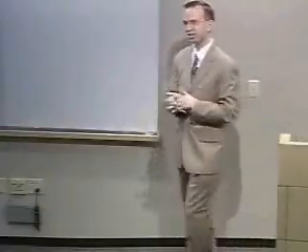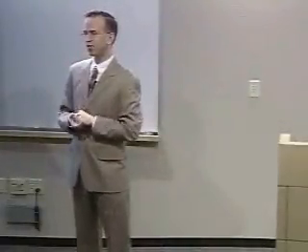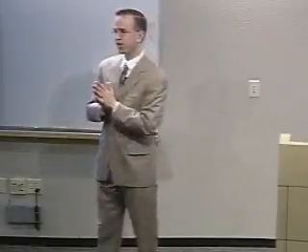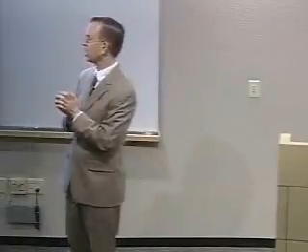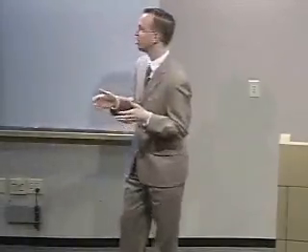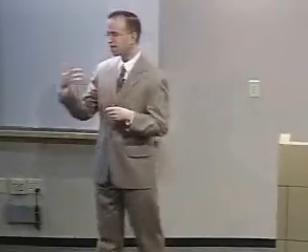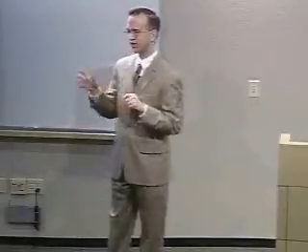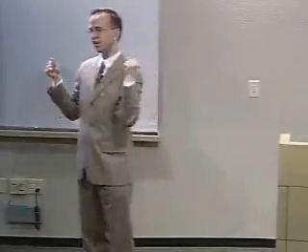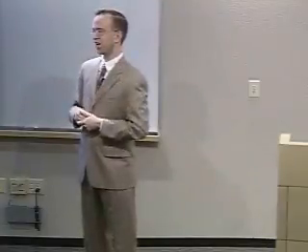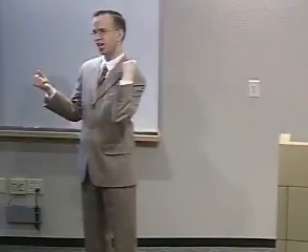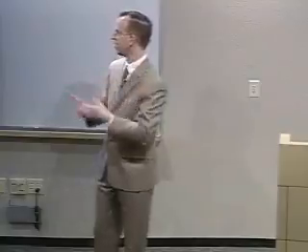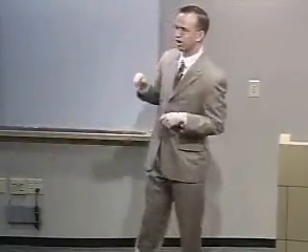All right, so now just to wrap up here, there's related work to what I've been talking about today. Of course, test beds are all related to this, and they complement this work as I discussed earlier. The closest technique to what I've been doing is that of channel emulators, which are used by the telecom community. They use the same fundamental technique. They digitize a wireless signal and send it between devices. They have a different target, which leads them to a different design. They are interested in very fine-grained modeling of a very small number of channels, usually one or a small number, between say a base station and a cellular handset. And the top-of-the-line channel emulator that I'm aware of is shown there on the right, the Proxim C8.